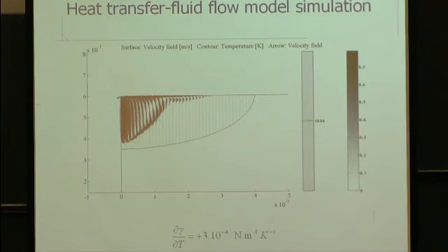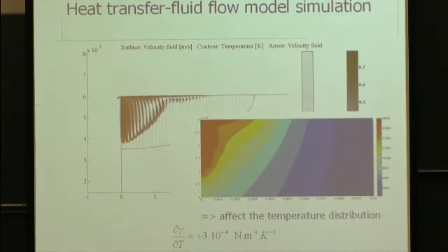So as I said, if you know all the parameters very well, you don't have any problem, you can do a simulation. One problem is we cannot really assess the heat flux on the top surface. So I described it with a Gaussian function with two parameters, but these two parameters are not known. And what I want to do is to identify these parameters, to estimate them with an inverse method. So what kind of information do I have? Basically, I will be able to do some temperature measurements within the material. And what I want to do is determine where I have to do this measurement to get more relevant information to do this estimation.